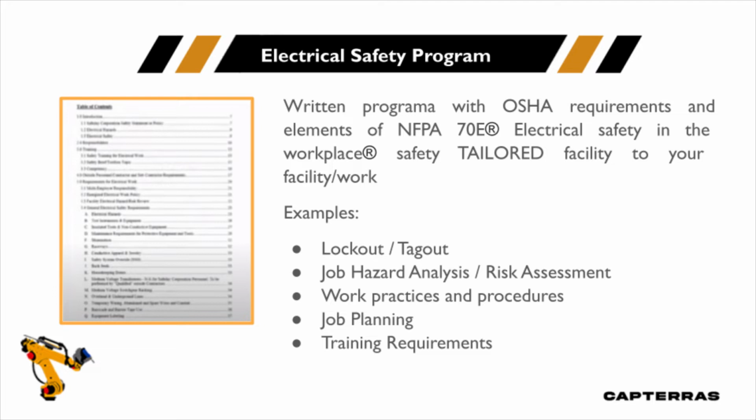In many cases, we want to have a paint-by-numbers approach. We want to tell everybody, well, if you put on level 2 PPE, if that's what's called for, you're good to go. Well, I want folks to understand and be able to make risk assessments and do job hazard analysis. So if we walk up to a piece of switchgear, we can decide what level of PPE is necessary. We can make good, educated decisions. You'll find that NFPA 70E calls for a risk assessment and OSHA calls for a job hazard analysis.